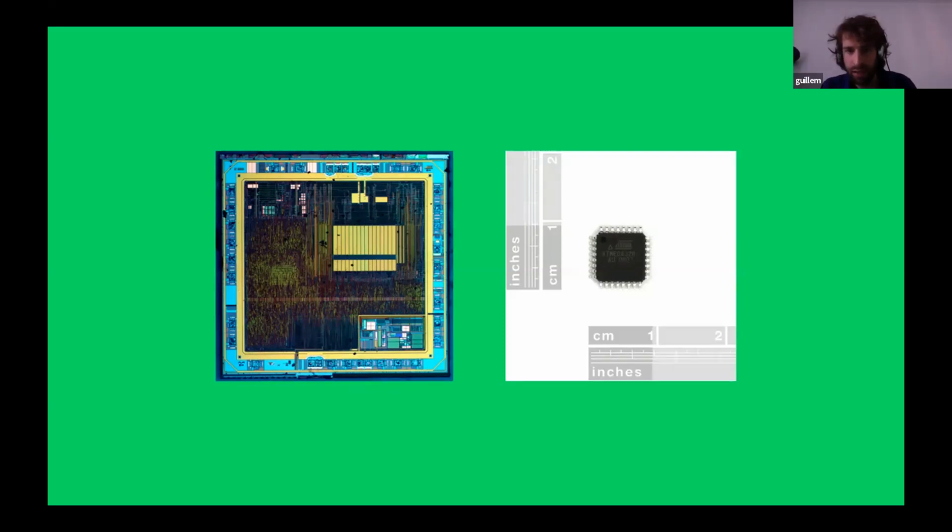The outside of this is not silicon, it's plastic, and sometimes it's ceramics, depending on the chip. If the chip is designed to work at high temperatures, it might be ceramics. If it's designed to work at medium temperatures, it's usually plastic. The silicon is inside it. You don't get to see the silicon. Usually it's a plastic, an epoxy, a resin layer. Edu, who's an expert on plastics and composites, much more than I am, could explain this better.